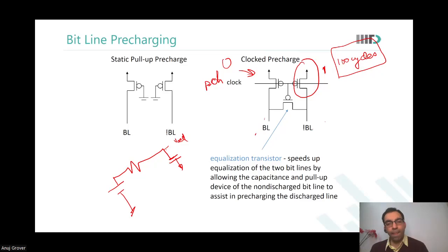So, sir, earlier you were saying that one bit line is at a lower level, because we discharge it through the write driver in the subsequent cycle and charge it again, but the other is maintained at VDD. So that one is able to reach VDD, but the other is not, because it is subsequently discharged at the right time. Yes, because for the past 100 cycles it was continuously in precharge mode. It never got discharged. So it had 100 cycles for charging the capacitor. It would charge closer to VDD, right? Whereas the other one was charged within just one nanosecond or less.